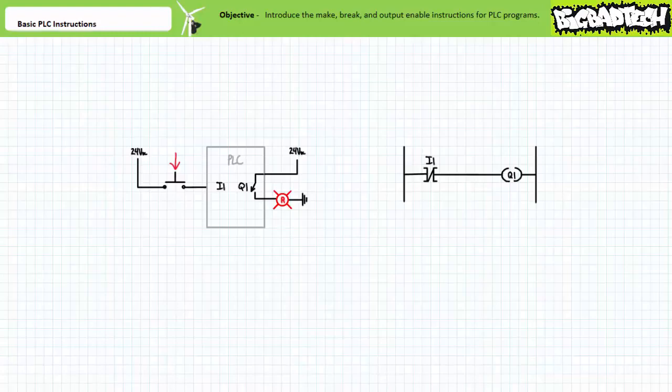The break instruction, in my experience, is one of the hardest scenarios for those just introduced to this topic to understand. Again, PLC program instructions have nothing to do with the electromechanical nature, normally open or normally closed, of the field input device. They simply respond to logical values as received by the inputs.